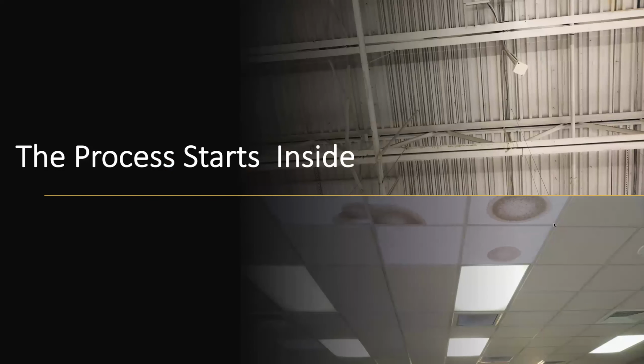Let's talk about a physical approach to the process of evaluating a roof. Either if you're doing this yourself or somebody on a team, perhaps as a guideline, or if you're contracting someone, what you should expect to see that they're doing if they're physically there on site, so that you're getting your money's worth. The process should start inside, looking at the underside of the deck. If you can see it, evidence of moisture entry through the deck or these bar joists, you'll see rusted spots. Perhaps like on the earlier picture, you start to see some stained tiles.